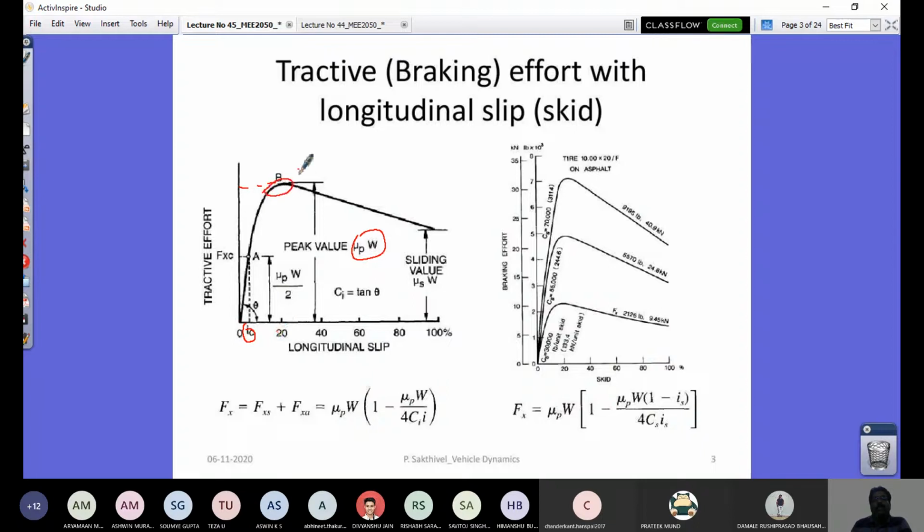That is where the traction control system plays a vital role, analogous to the anti-lock brake system that you have seen. It would ensure that your tire will not completely slide. There is a portion of the contact patch which should slide, which should slip.